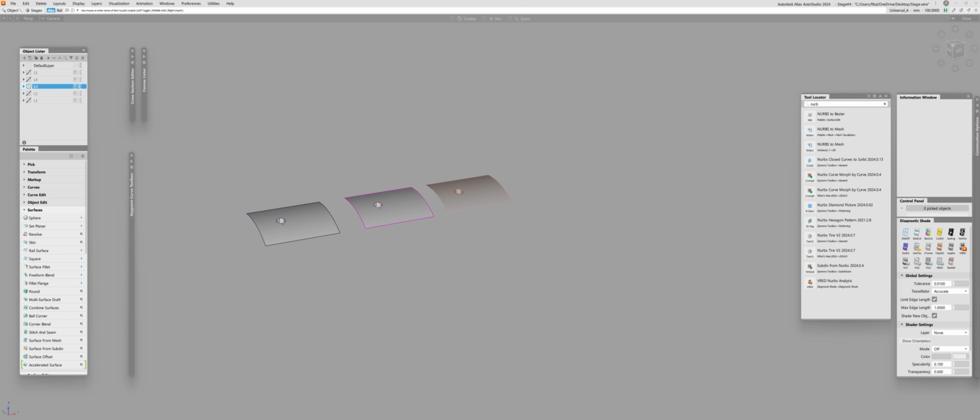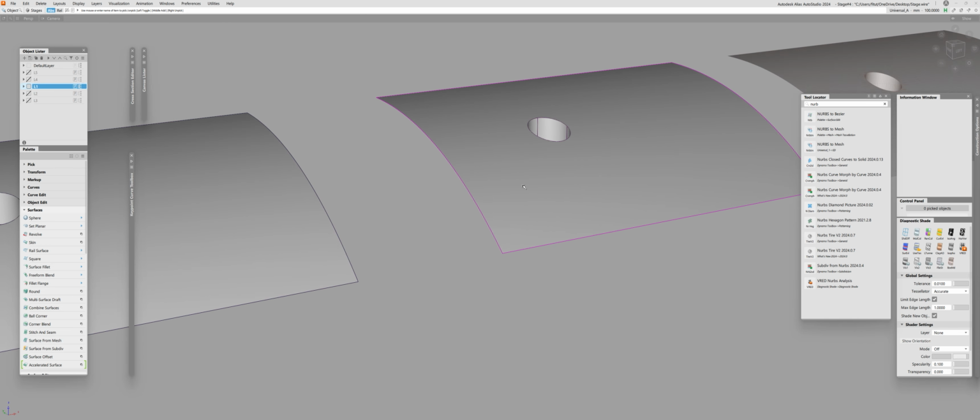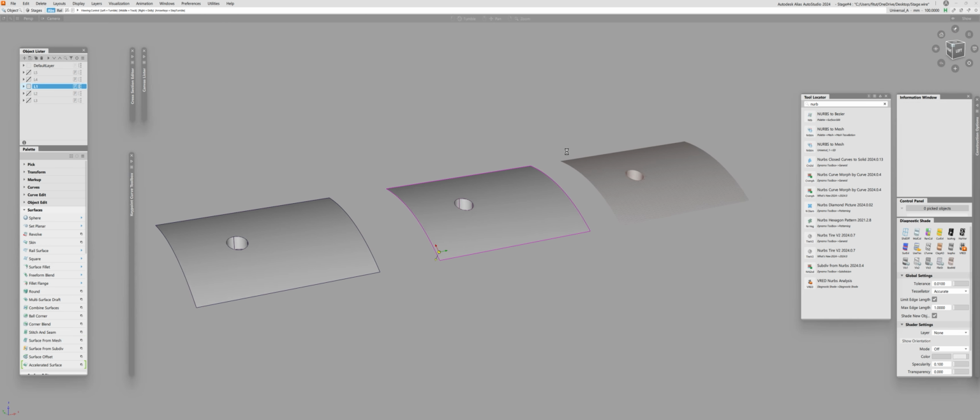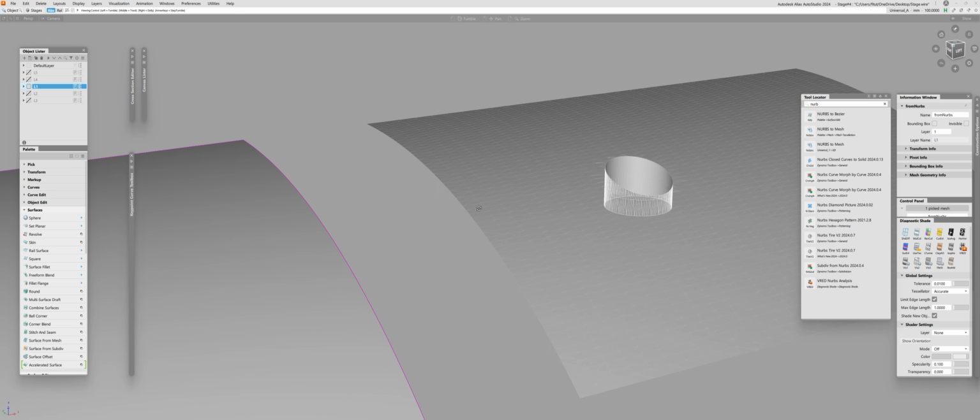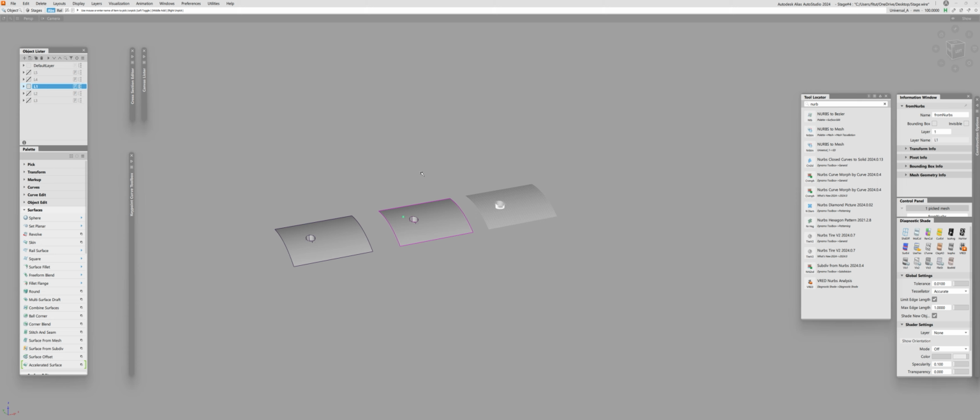But there are a few others like Hoops, Cutfix, Meshmatic, Polygonica. I believe you can find more by just Googling them and try them out, but I will focus on Pixyz in this lesson. One of the benefits of the external tessellators is that you don't really need to take your model, stitch it to create a binary representation, tessellate it piece by piece, and export each piece separately. You see how many steps you need to do to create even a somewhat decent result like this one, right? And you need to do it for everything, and your model may have thousands of pieces.